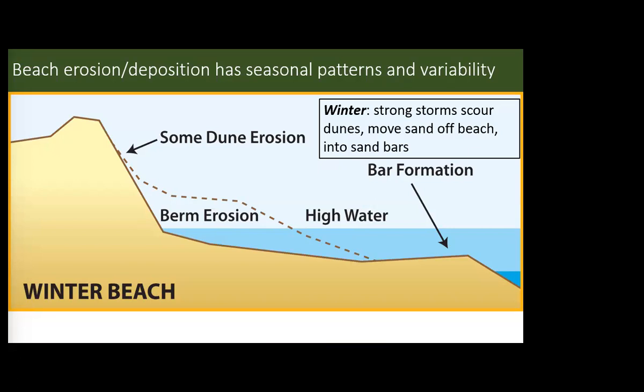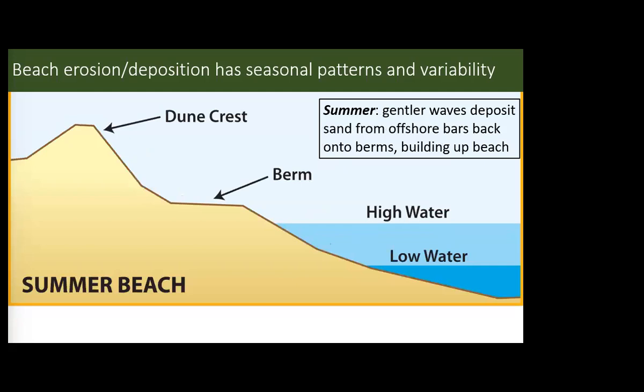But during the summer months, that dune is going to eventually fall over, replace the berm, and eventually from wind, from wave action, it's going to build the dune back up. So in this natural system, even though it's going to be moving around, the dune helps to replenish the berms. It helps to provide this equilibrium of deposition and erosion.